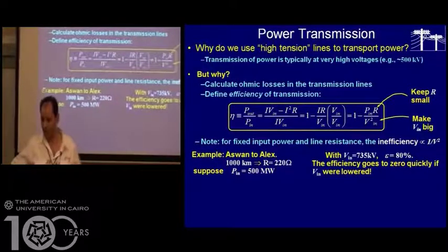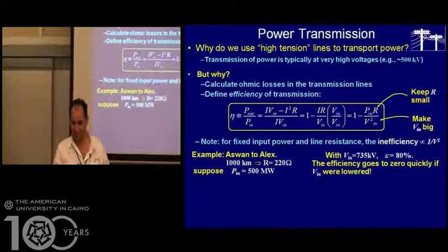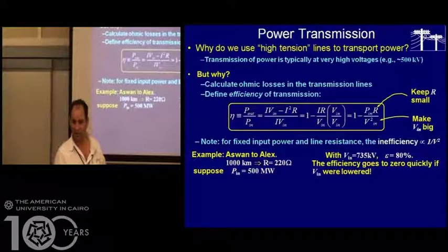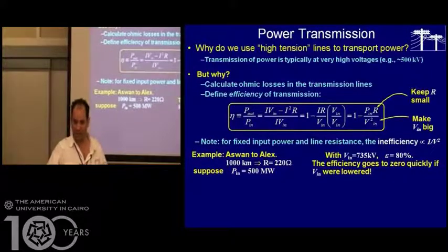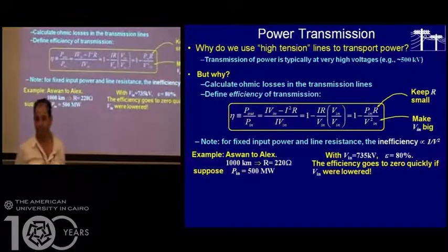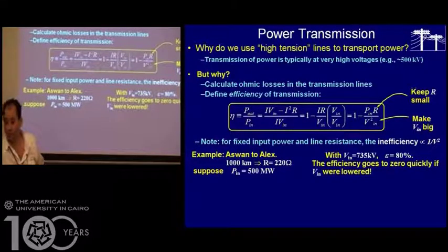If you hold any wire covered by plastic or something, you feel it's going to be hot. Your computer gets hot all the time because of the current that flows in it, and this is mainly I squared R. IR is the potential drop, not the power.